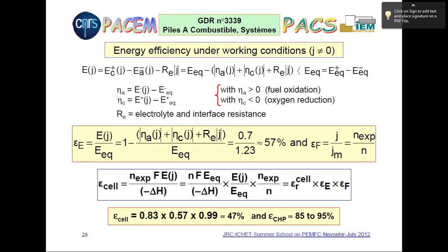But now if you take an internal combustion engine, 100 kilowatt, you have one third at maximum as mechanical work, I would say 30 kilowatt or 20 kilowatt, and one third as exhaust goes to the air, and the other third is exchanged with the cooling radiator.